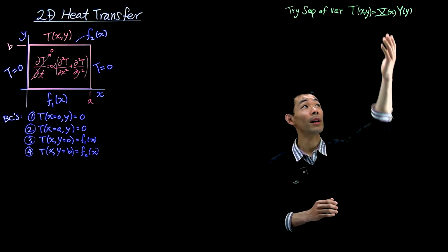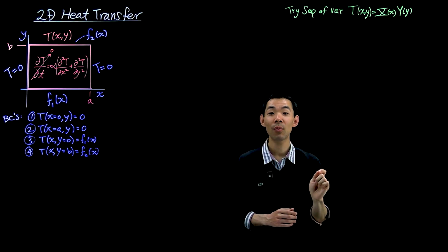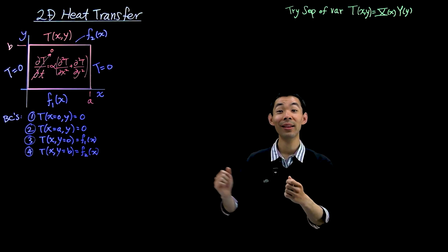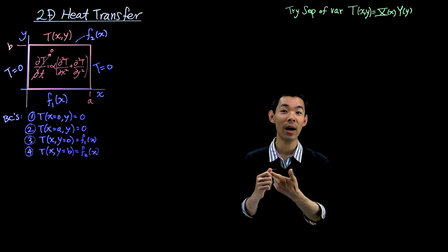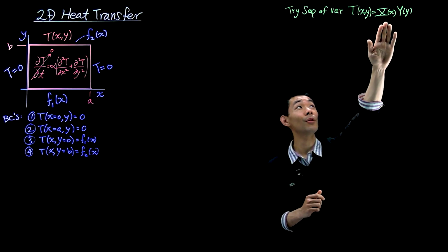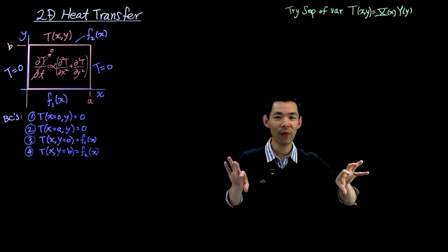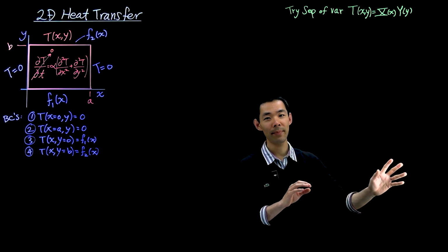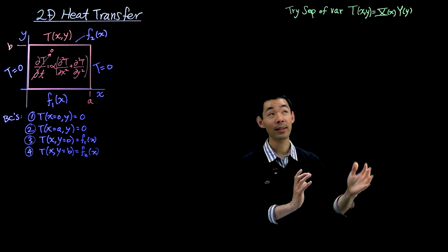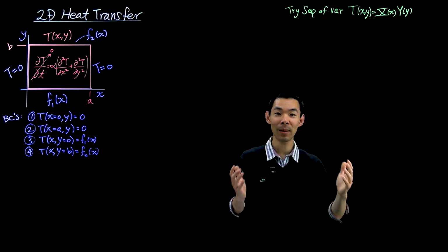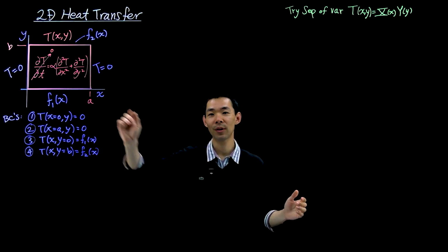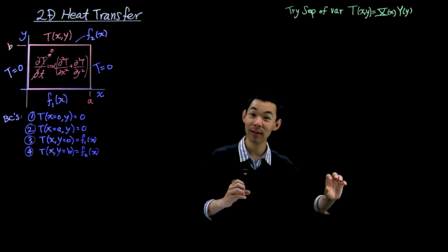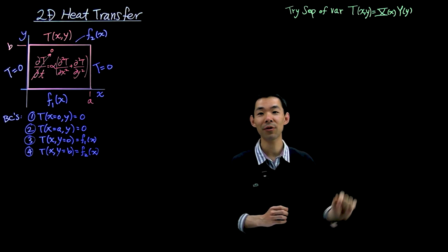So previously, we did capital X times theta, which was a function of time t. But in this particular case, there is no time. And therefore, we have position x and position y, which are independent variables. So we're taking two functions, each only a function of its own independent variable, position x and position y, taking the product of those two things and declaring that as our overall temperature profile in the steady state case for this problem. So it's still a guess that we can write it and separate the variables, right? That's why it's called separation of variables.